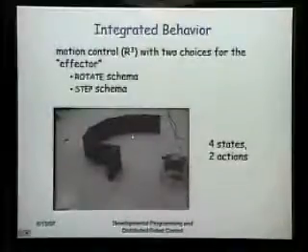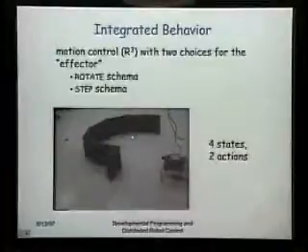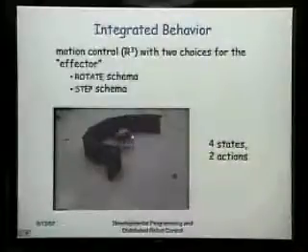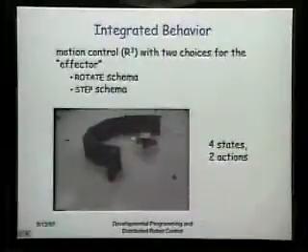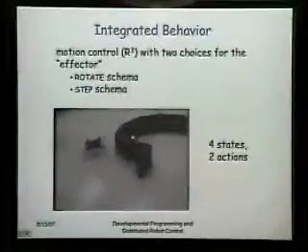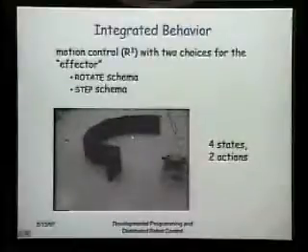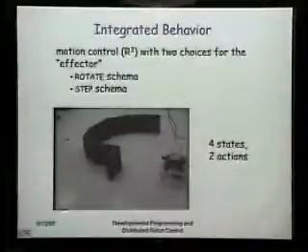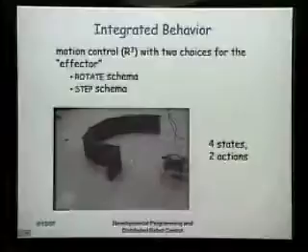And what you see here is the real learning response. You wrote the program in the context of this single trial. It notices things. It puts them in. Oh, we have one more controller I forgot to mention. There's a harmonic function controller, which is a path planner. And so it tries to go straight to the X, notices an obstacle, then it tries to circumvent the obstacle, and it does that recursively. And all the step and rotate have to do is figure out when it should be stepping and when it should be rotating. I'll play that again. It's got 4 states, 2 macro actions.